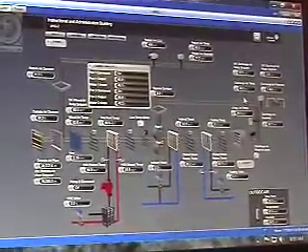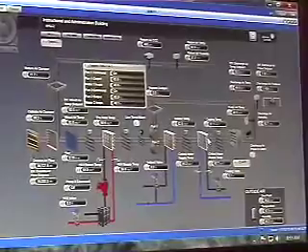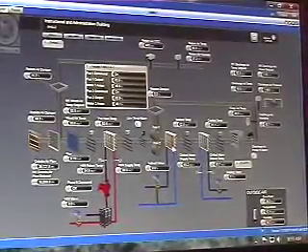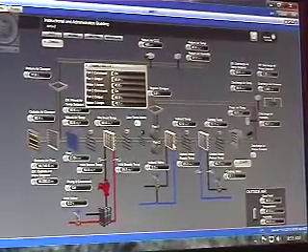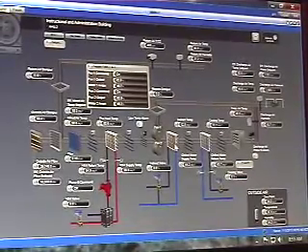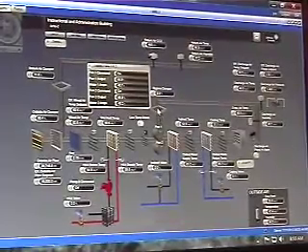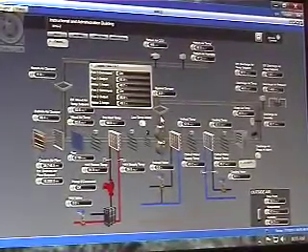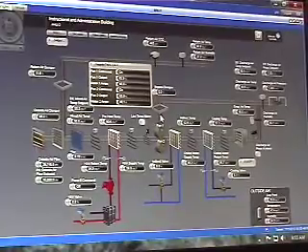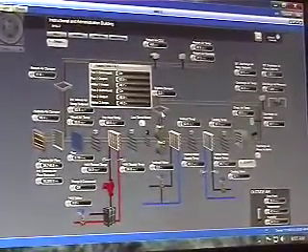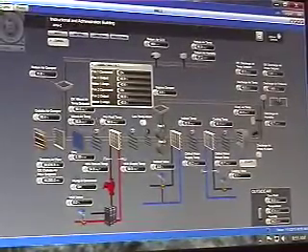To go down the other way, when this cooling valve gets below 5% open, we then will switch to state 4, which goes back to this coil. When this coil is open less than 5%, we then switch back to state 3. So now we're controlling out this bypass. We then will stay in that mode until the outside air temperature is below what our mixed air set point is, which will then switch back to economizer, which is state 2.